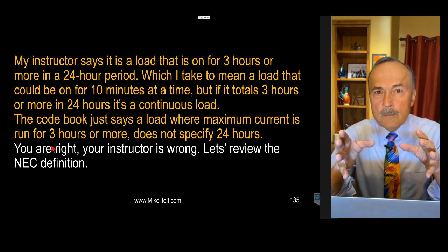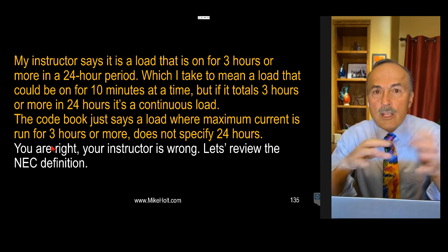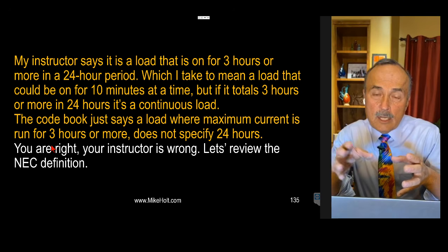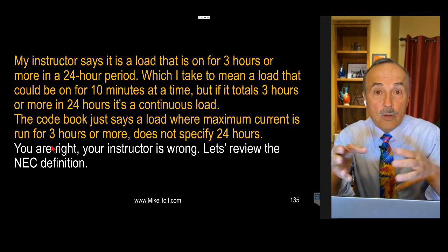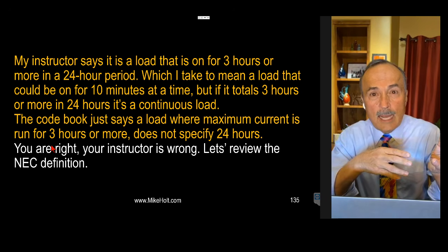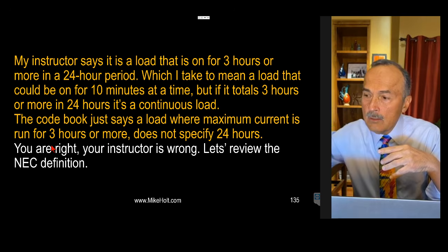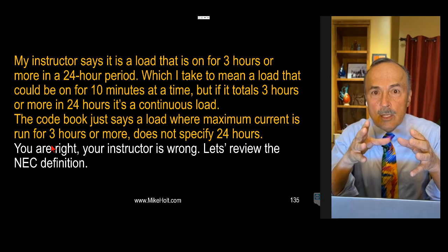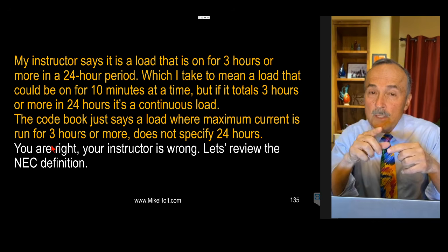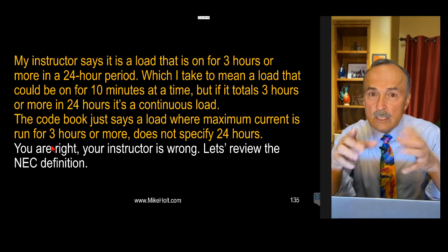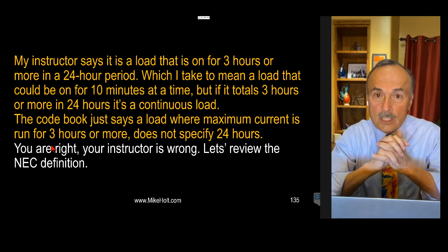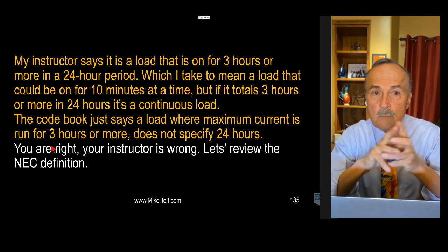Why is that important? Because when you carry current on a conductor, it ultimately creates heat. The greater the current, it's called I squared R. We covered that in our theory. The higher the current, it's I squared, which means you're squaring the current times the resistance, and that's where you're going to get your heat, and it's called power. It's a function of time. In other words, you can get something to happen so fast.